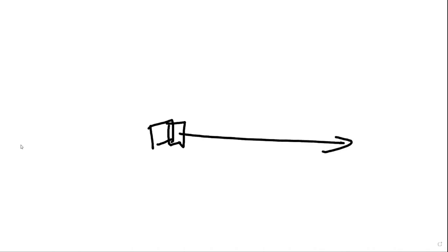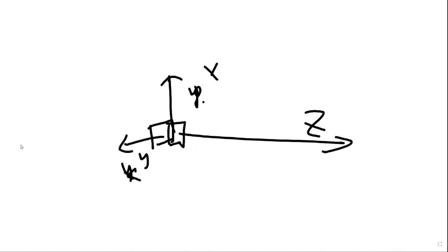If your joint is prismatic, that's an extender, and then you extend in this direction. So this should be Z. X should be this one, Y should be this one, because you need to cross product using the right-hand rule. Okay, so that's what the right-hand rule should be.